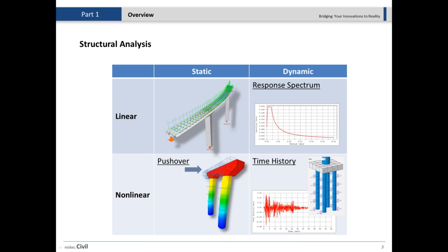So these two types that I mentioned about the dynamic analysis, response spectrum and time history, those are run on the structure to find out the demand on the structure. So by demand, I mean what will be the total displacements, like deformations, all the internal forces, what will be the response of a structure to that type of loading.